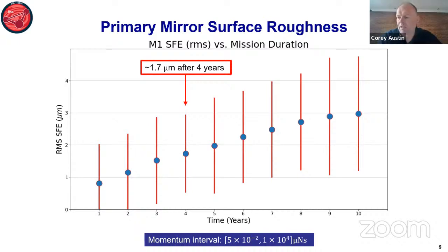Yeah, it's something that internally we've talked about a little bit, not so much along those lines, but more that when we coat the mirror, there's going to be some tension, for lack of a better word. The coating is going to change the surface figure of the mirror, and as we impact the mirror, we may, forgive my hand-wavy term, release some of that tension and change the overall curvature of the mirror. That's one thing we want to think about. Certainly cracking and things like that would be a concern.